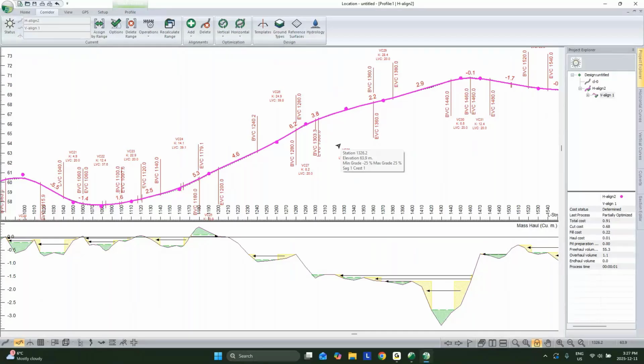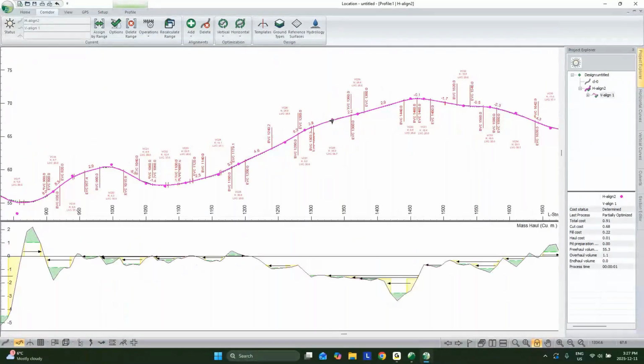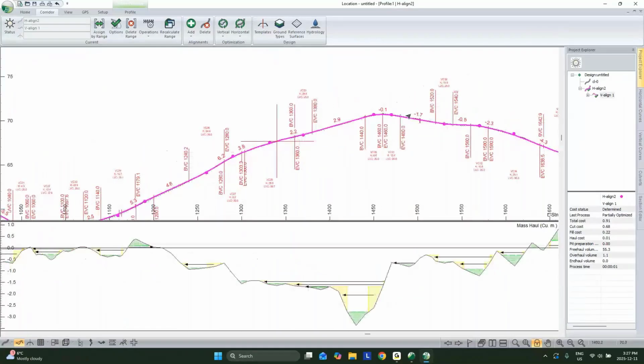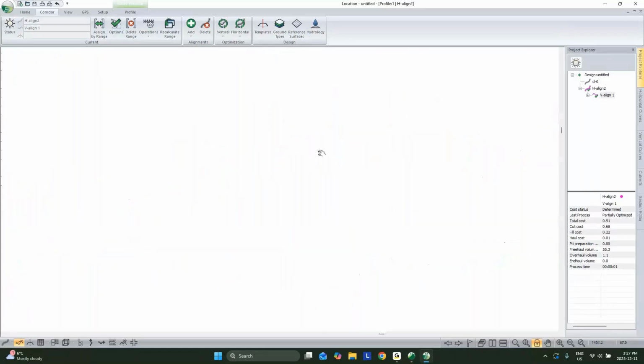And if we kind of go back to here, well, even if we don't do anything to our alignment, we still have to do a lot of excavation to lay back those cut slopes. So maybe it makes sense to realign this. Now from about here on, we see that we're tracking the ground very close. I've got one tight curve, but I can live with that.